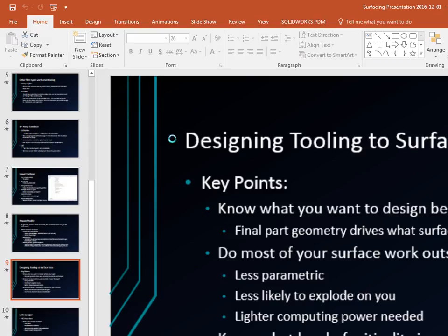Are you guys familiar with the selection manager for picking edges? This is a really useful tool when you're doing either a loft or a boundary surface or a sweep, if you want to take multiple edges and use them as a single entity. On a lofted surface, I could do a single loft here, a single loft there, and a single loft here. Or I could loft and use selection manager to pick these 3 edges, and now boom, it's one entity.